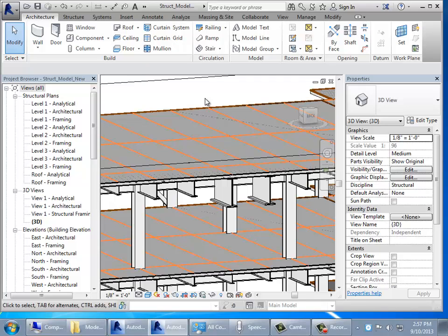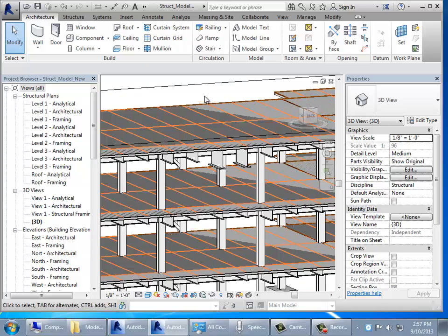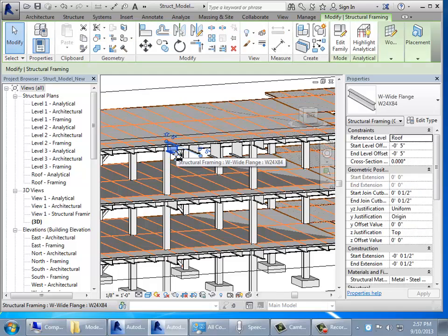Try changing that. Okay. Let me tell you what's going on, because I actually do know now that I saw what your question was. Here's the deal, just a little preview of where we're going. The beams which are actually lined up with the columns are individual beams. Those are like girders collecting loads from other things. The little intermediate ones are part of a system, and they're pinned because typically you put all the intermediate ones the same size, so if I want to change the entire system I can, or not. But it wasn't pinned ultimately because it wasn't locked.